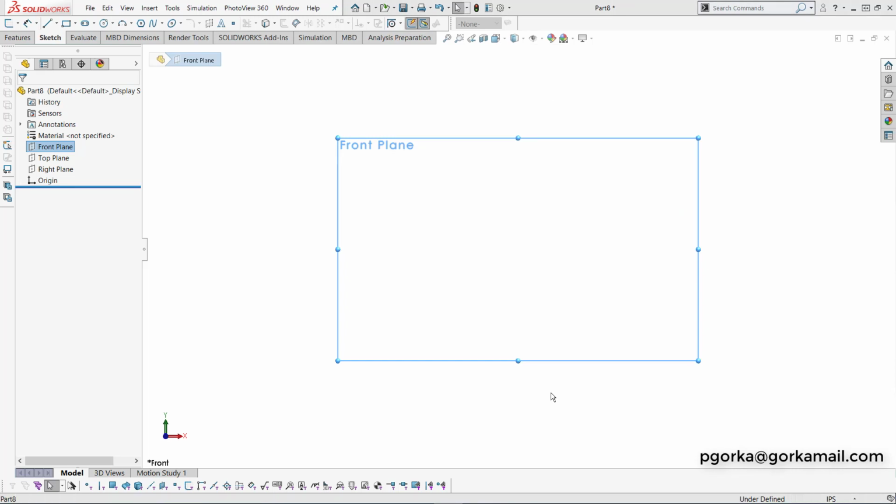With my virtual piece of paper ready, I will start creating my sketch. I could go to Sketch, Create a Sketch, and that would start the sketching process, as long as you have the plane selected like I do. However, I could also click on one of the sketch commands, and the system will know to create a sketch entity for me. So let's click on the line command.